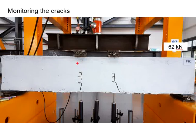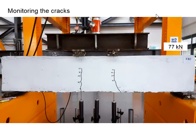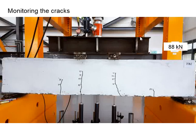Normally, the first crack will happen at the midspan. As the load increases further, more cracks will occur. The cracks propagate deeper and deeper into the beam as the vertical load increases. After the first crack, there may be additional cracks at an offset distance from the first crack, closer towards the support. The same goes for the other side.